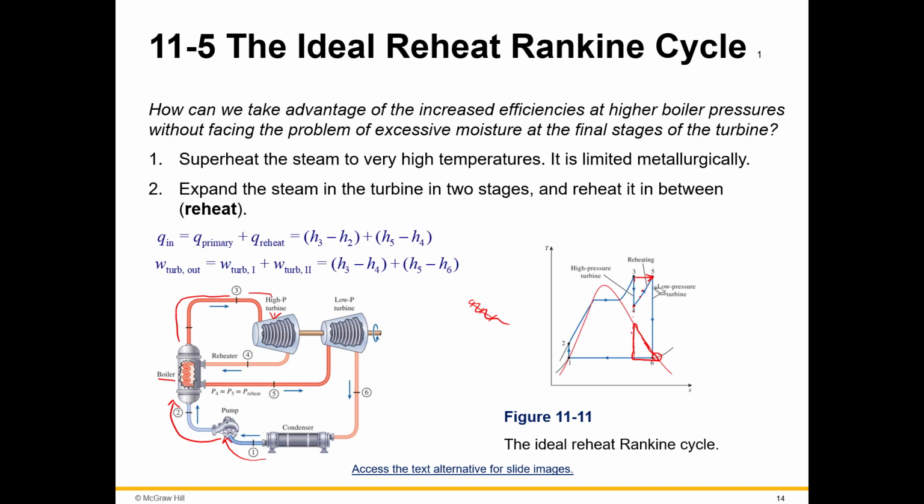Let me erase these off so that you can see what we've done so far. Okay. So from 1 to 2, we've gone into a pump and we've increased the temperature just a little bit, not a whole lot. But then 2 to 3, we are increasing the temperature a ton, right? Because we went to the boiler. 2 to 3, we went through the boiler.